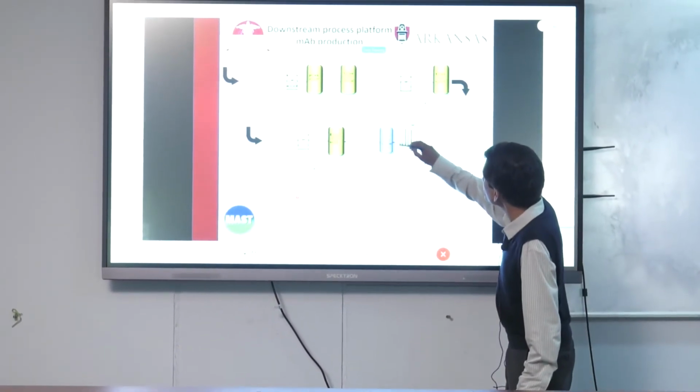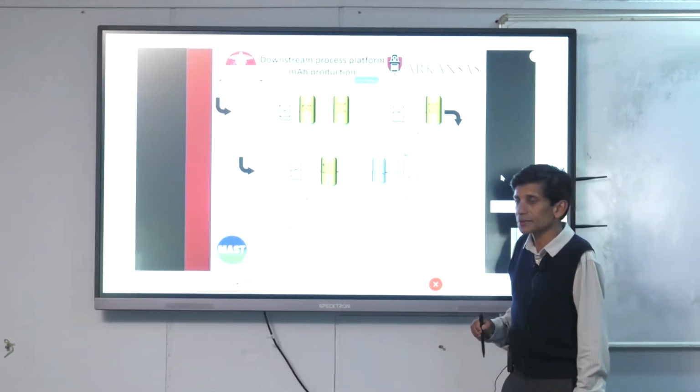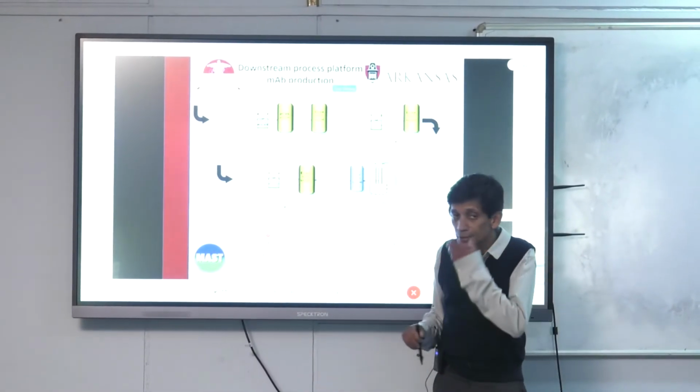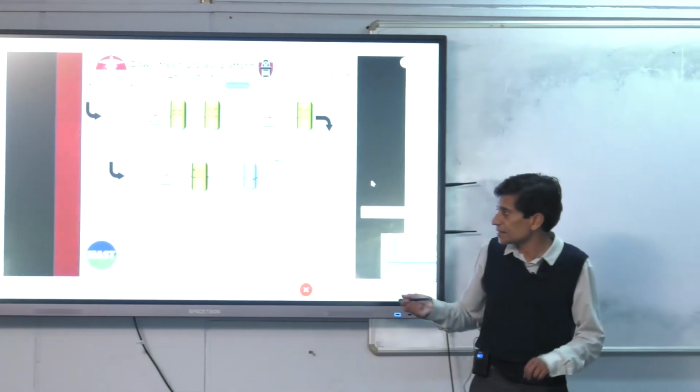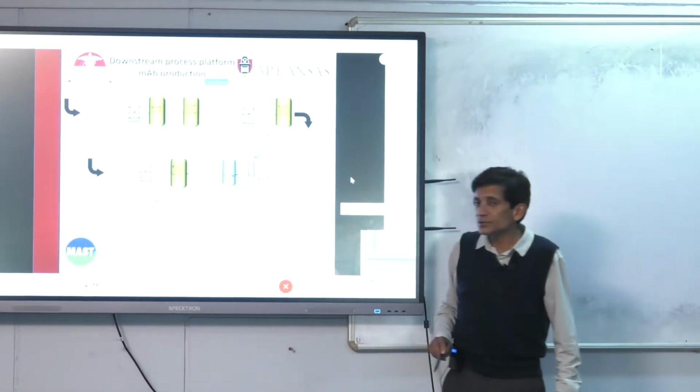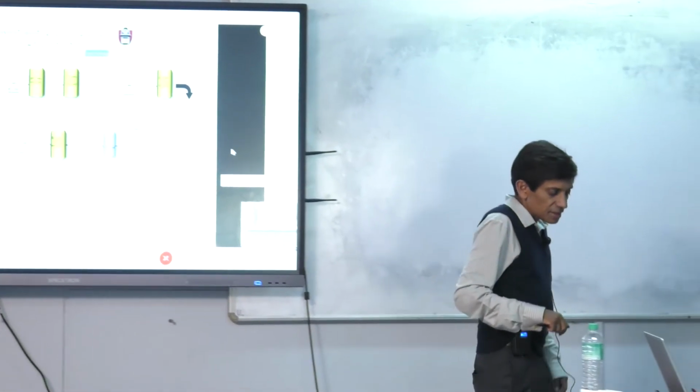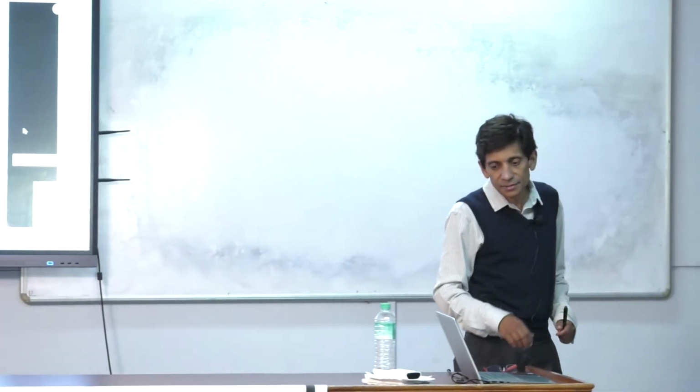because here we have an ultrafiltration diafiltration step. Now you may have, it doesn't show it here, other concentration steps anywhere in the process, but you always tend to have one at the end because you want to put it into your final formulation buffer.